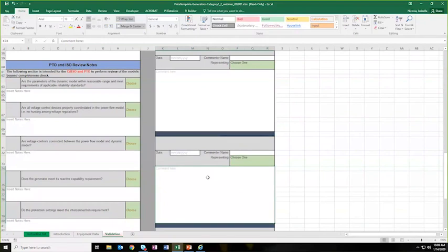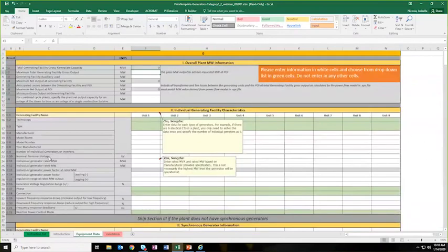Yes, under the equipment tab, the discussion that we had a minute ago, I have a question under the plant megawatts. We do have a synchronous generator that operates very near unity power factor. That's how it's dispatched by the transmission operator. During high flow conditions, it's a hydro unit. In the springtime, we go to 54 megawatts on a 55 MVA machine. So is it appropriate to put 54 megawatts there, even though the rated is 46.75 at an 0.85 power factor? Yeah, 54 is fine.